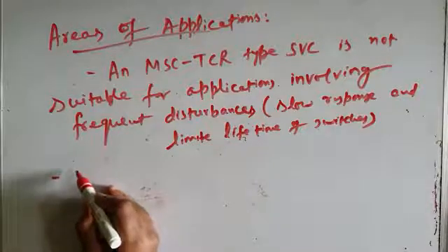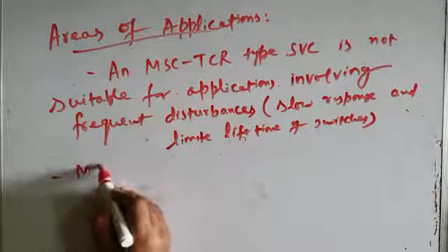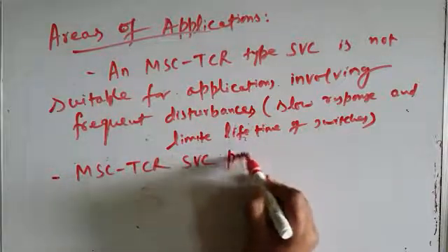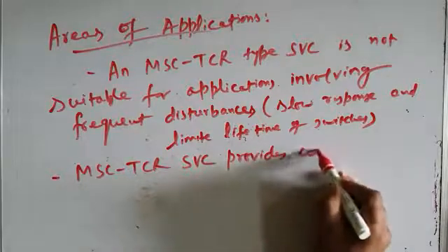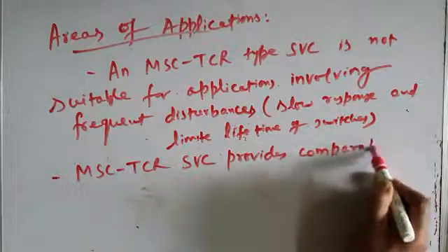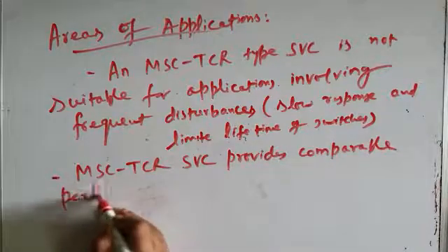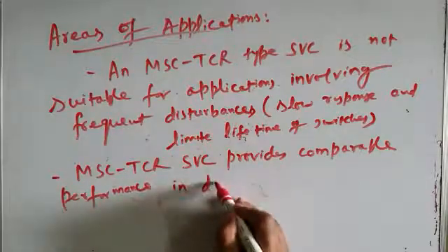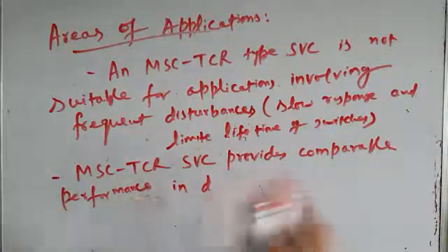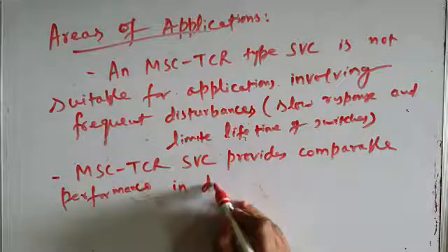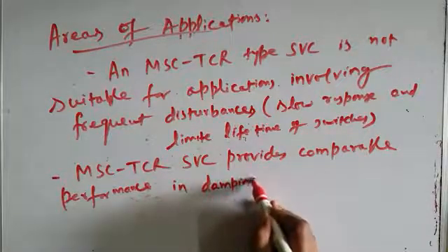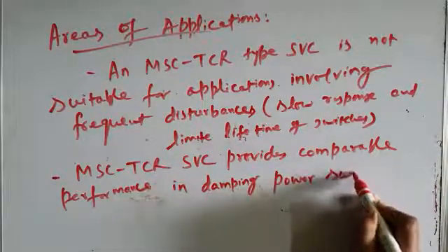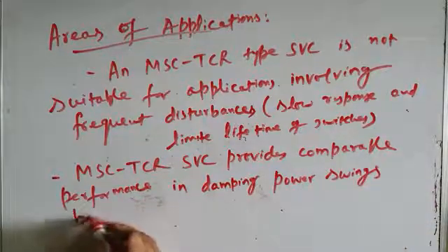So therefore, the application is: MSC TCR SVC provides comparable performance, compared to TSC TCR SVC, in damping power swings between two areas.